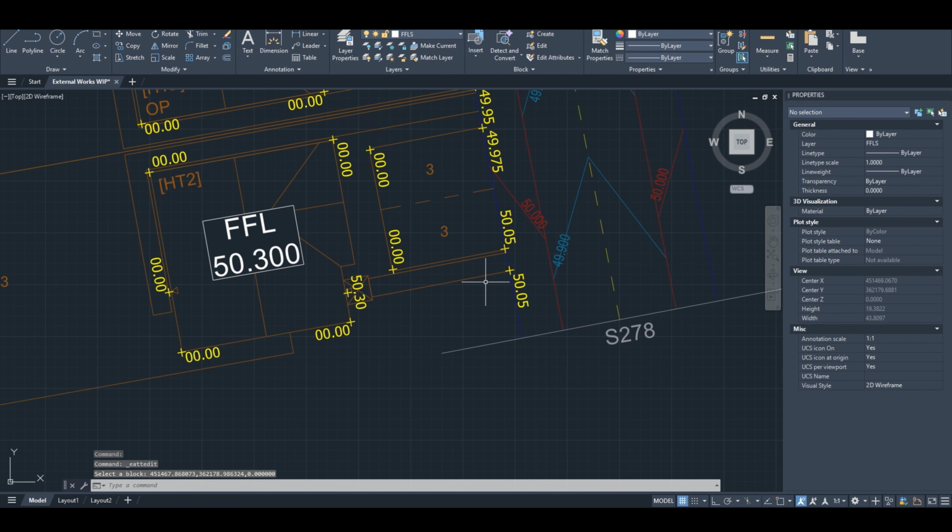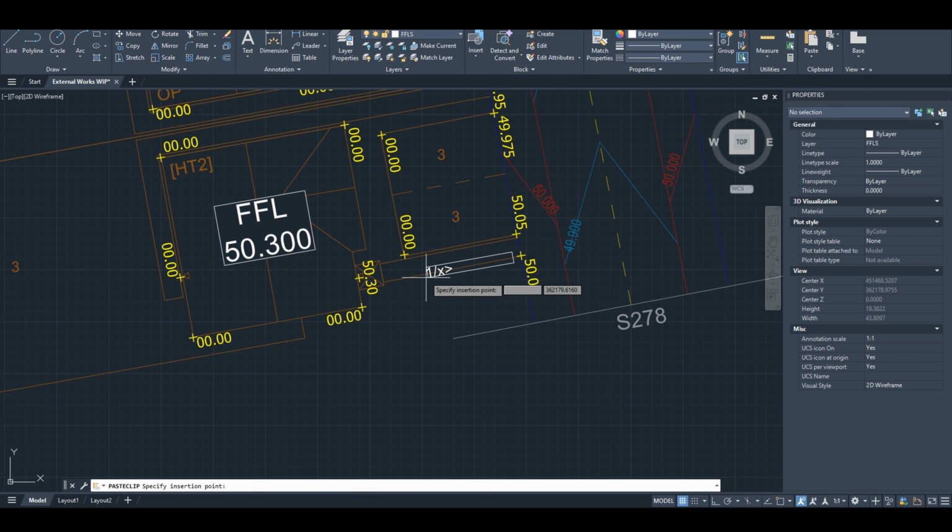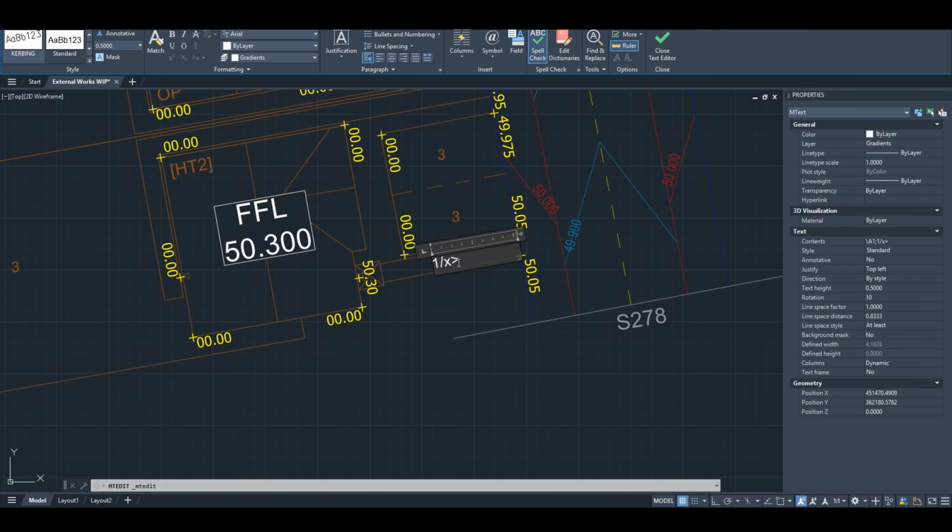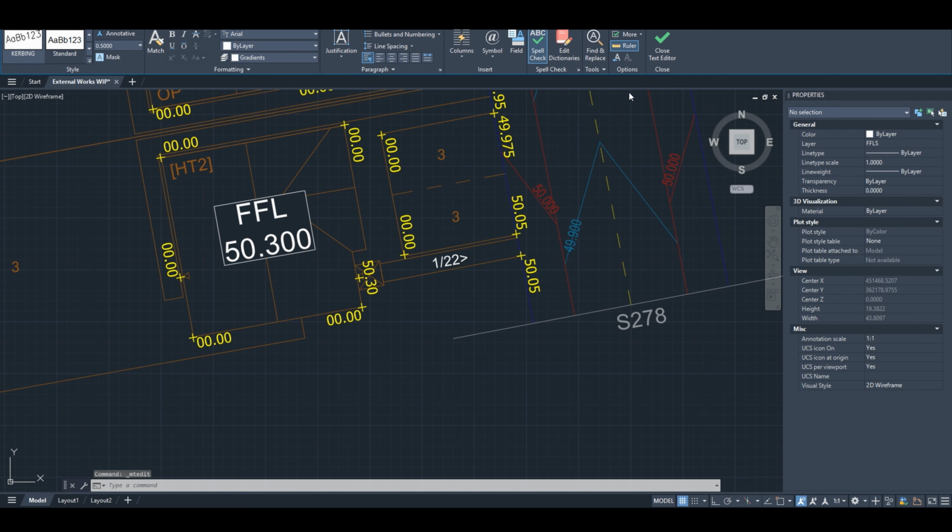We then need to check the gradient of the path to see if it is not steeper than the maximum gradient. Refer to Part M guidance for more detail, but generally try to have a maximum gradient of 1 in 20. If your path is steeper than this, refer to the section of the provided cheat sheet regarding the main entrance hierarchy. Annotate this gradient down the path. The arrow should be pointing down the slope.